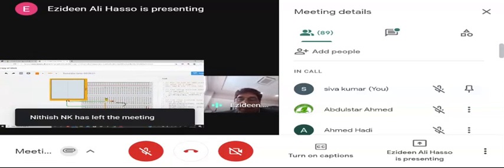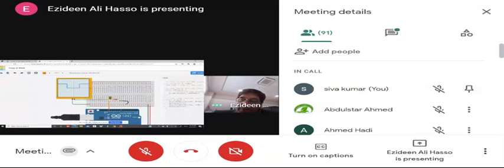If I start the simulation, you can see the blinking, 1 second on, 1 second off. This is 4 divisions, and we said each division is 0.5 seconds, so we have 4 divisions off and 4 divisions on. So it is working as we intended.